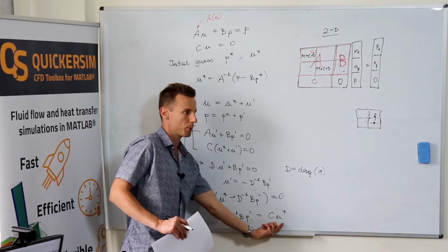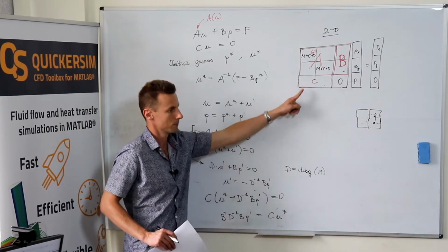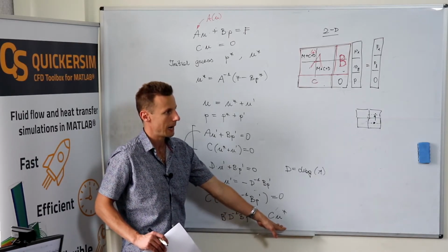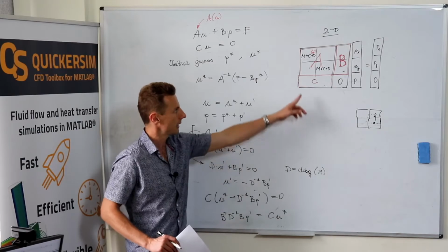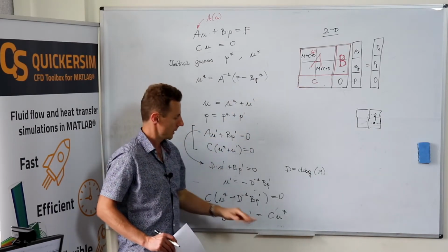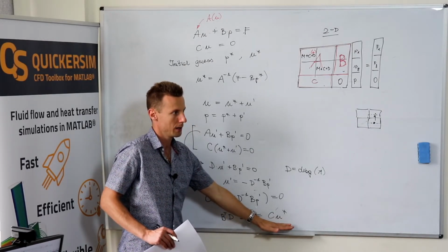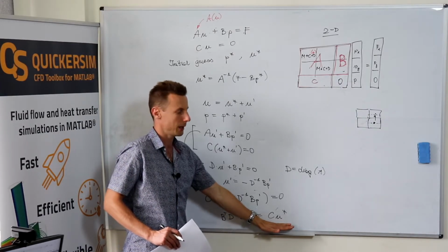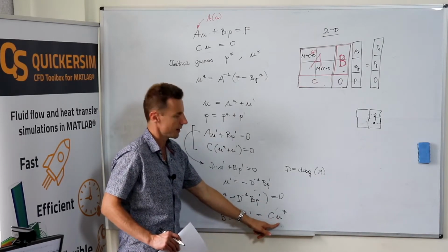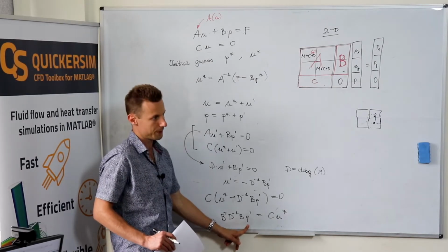What does this term represent? The divergence of the velocity. Exactly. This term represents how divergent your current velocity approximation field is. If it's 0, then you have already fulfilled the divergence-free condition, and a 0 right-hand side for the linear system means a 0 solution vector, and that's true.